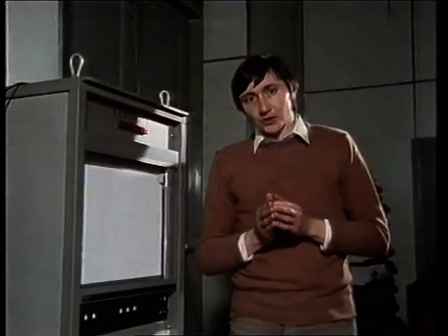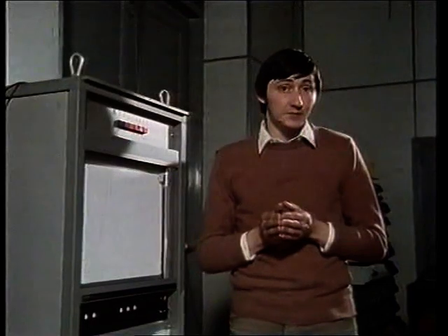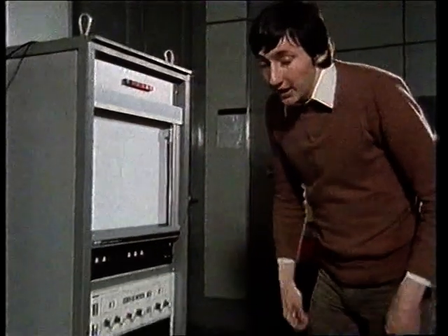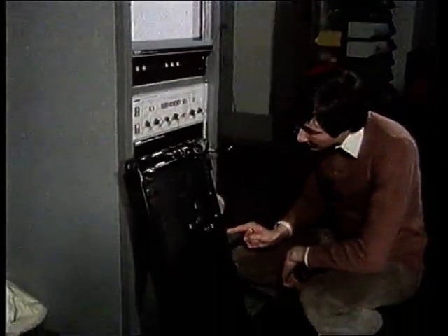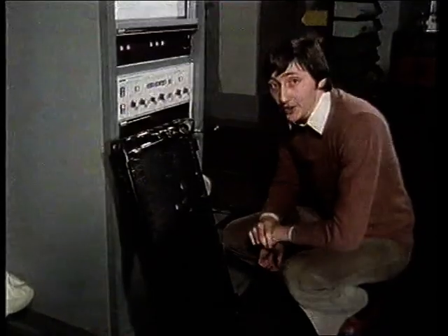They don't particularly want to change the design of the tubing, because that would affect the heat transfer characteristics. And as a radiator, they're quite happy with it. What they decided to do was to increase the damping. And they did that by clamping the honeycomb much more firmly between the top and bottom plates. And this design of radiator may not look very different, but let's look at the transmissibility.